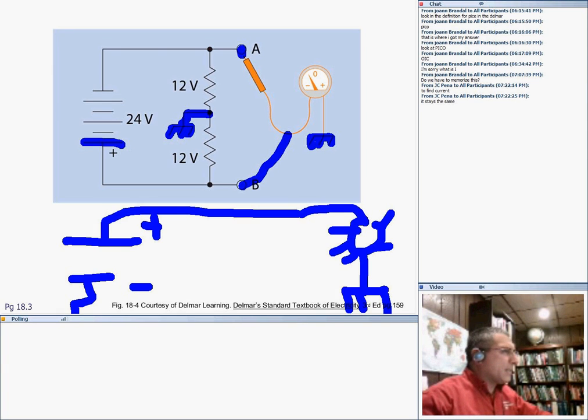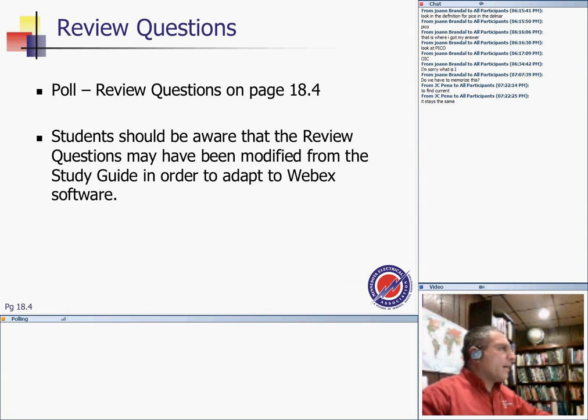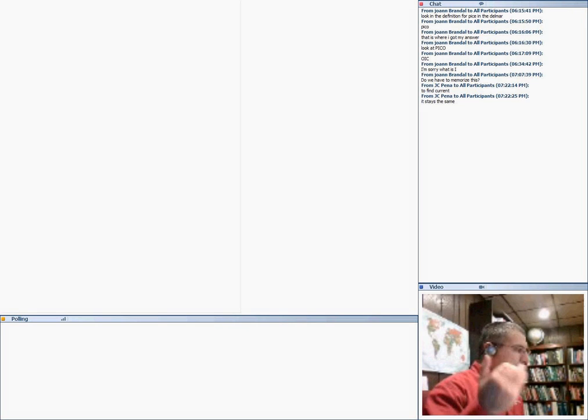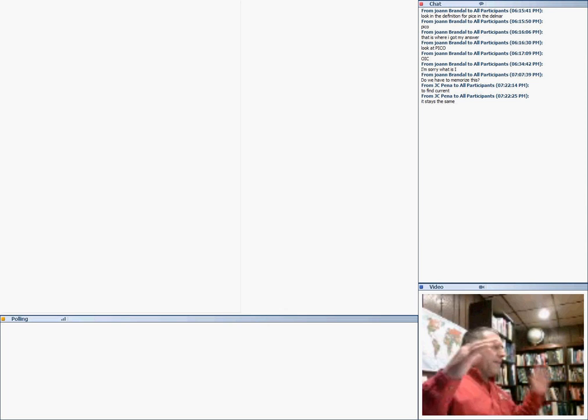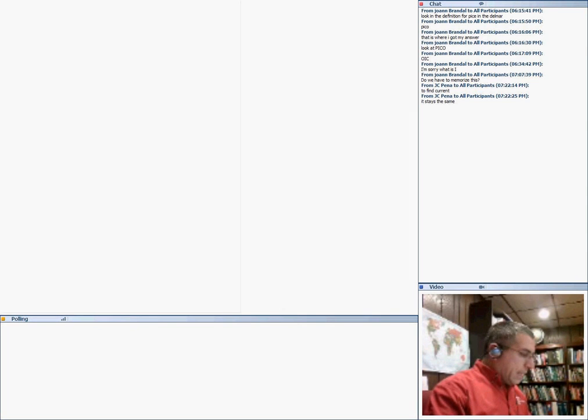The automobile industry uses some type of system like this, guys, where you use the frame of the automobile as the reference point. They are connected through the frame. You can't use this in the power industry. You have to pull a neutral from here. So just FYI, remember the reference point in DC could be the frame of the automobile. For us in the industry, we reference to the ground, guys. I wanted to mention that before I forget.